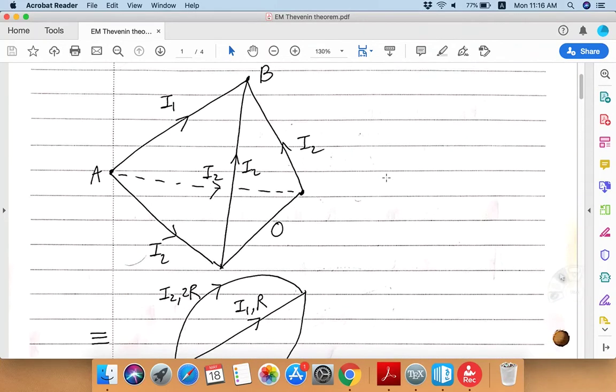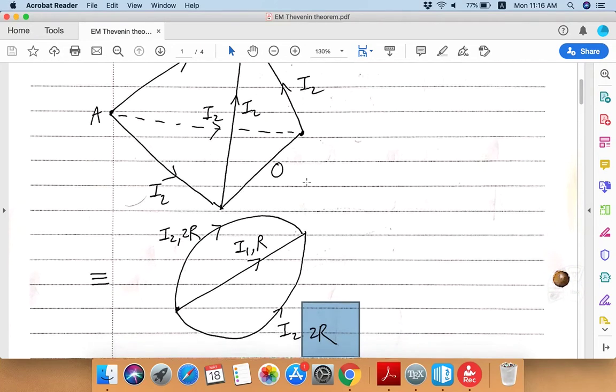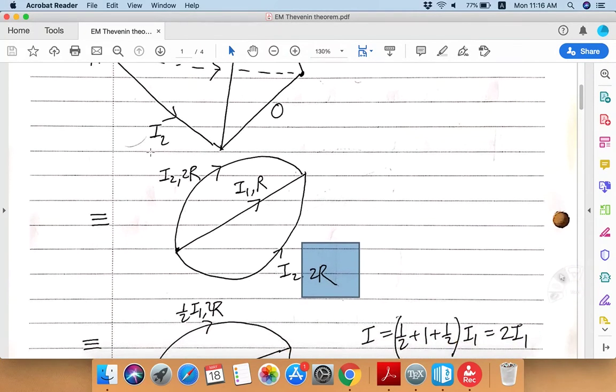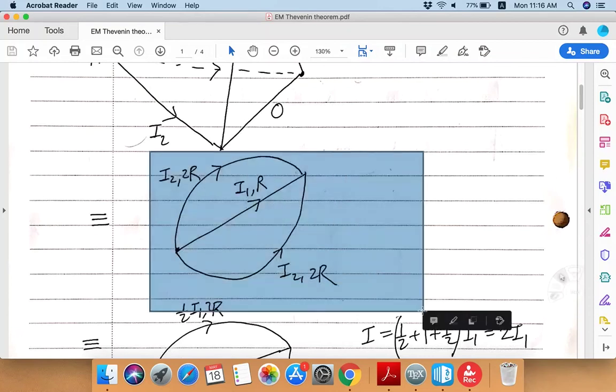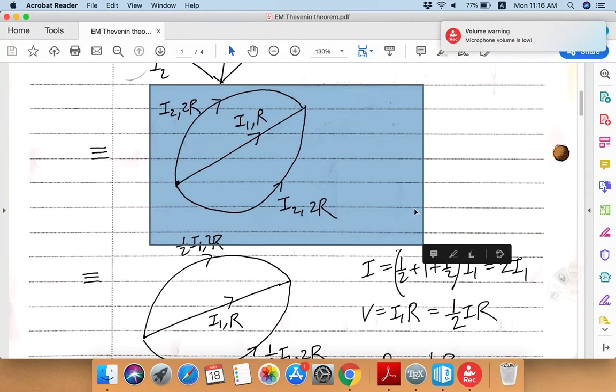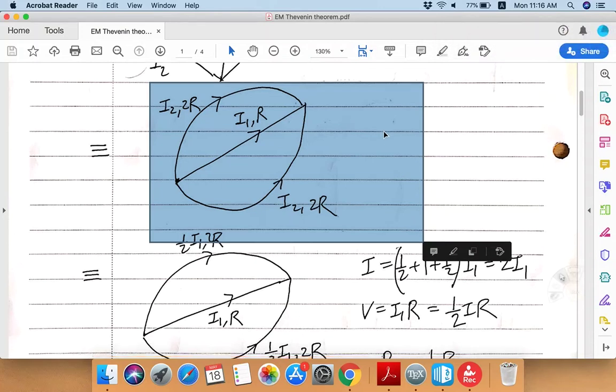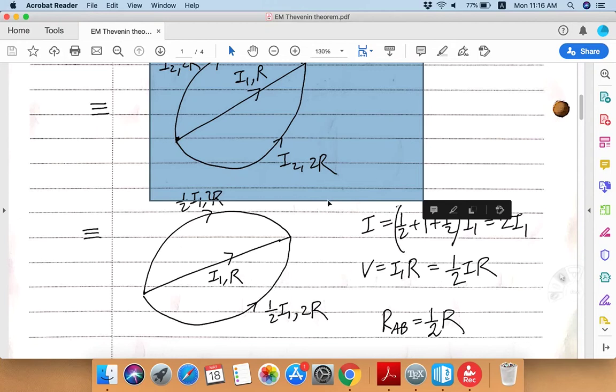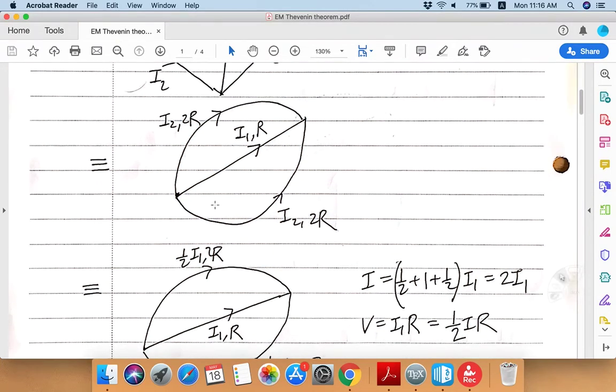Okay, so at the beginning we started out with this three-dimensional resistor network. But then we were able to immediately reduce that problem to that of some two-dimensional resistor network like this. Okay, and this is pretty simple to analyze if you think just a little bit about it, since the voltage drop from A to B must be the same no matter which path you choose to follow.